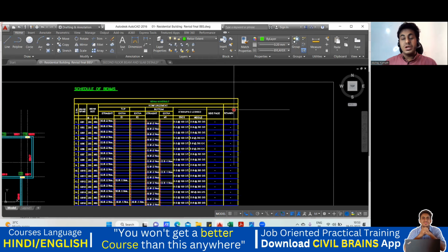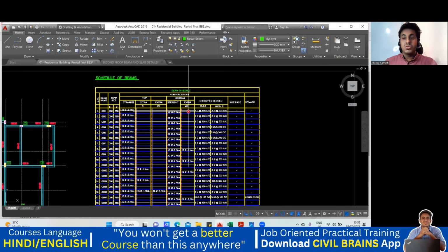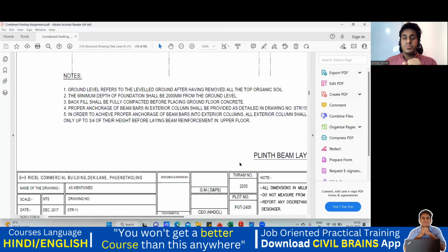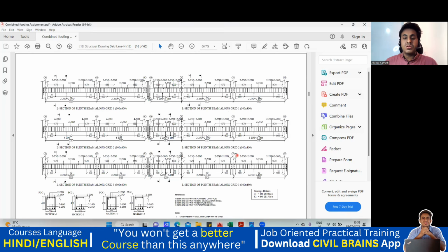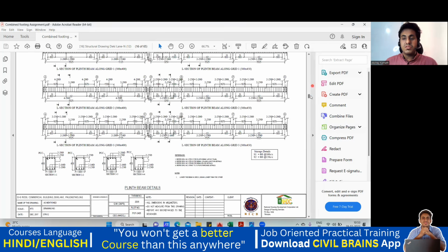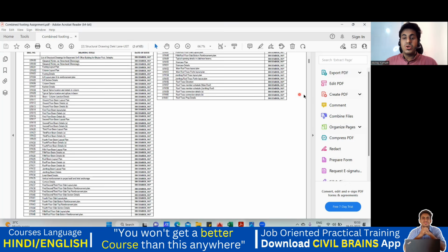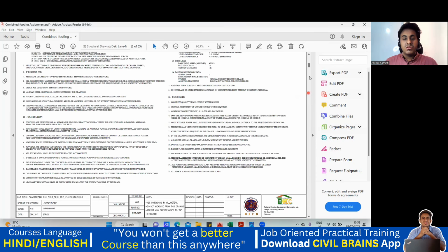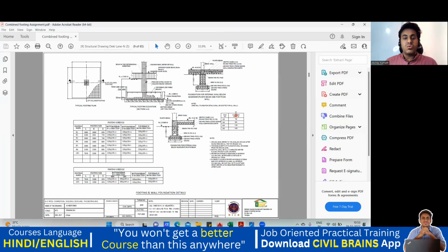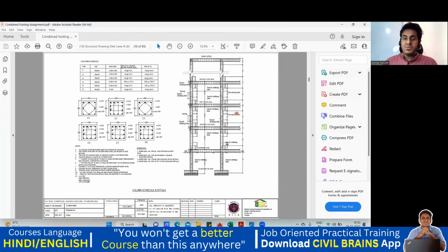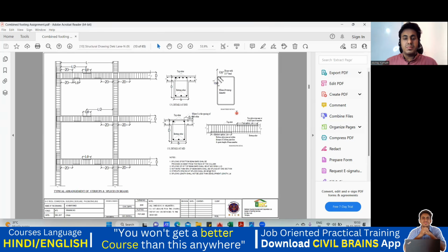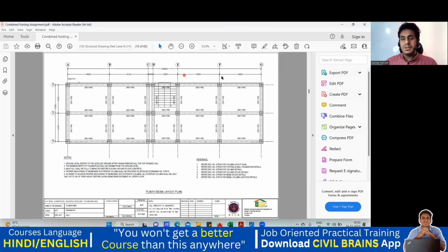So since we are doing it for the first time, it will be very difficult for me to teach you all these things. So what I'm going to do, I'll take this particular project because I had given it to you, and this is the same project. It's a G+5 story building where I had given you a lot of assignments to be done. For the same building, I'll teach you how the beam BBS has to be done. This entire plinth beam layout, I'm going to teach you for the complete thing.